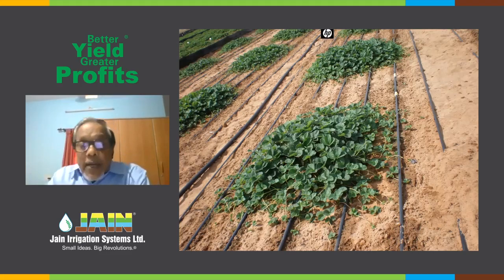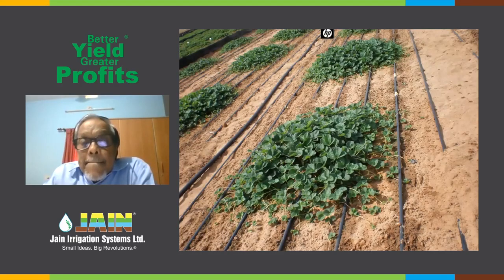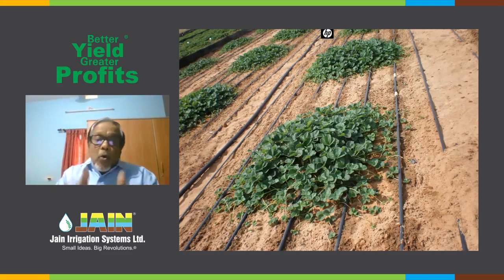Many places you can see that actually. This is what I said, loading the soil or field with more plastic. Certainly it's not required for uniform irrigation. Certainly compared to a clay soil, you need closer drip lines in this. I am not denying that.